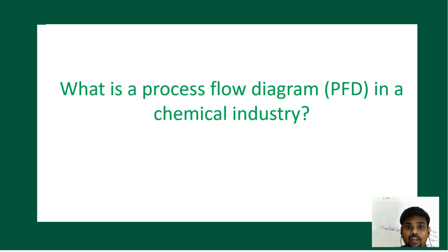Also, these process flow diagrams can be as simple as that, or they can be even more detailed, including, for example, process control and process instrumentation. We can include such minute details of instruments attached. For example, if it's a reactor, a temperature measuring device and pressure measuring devices may be there. In that case we may even go for process instrumentation, right? These process flow sheets are the basis for instrumentation engineers to add process instrumentation to the system.